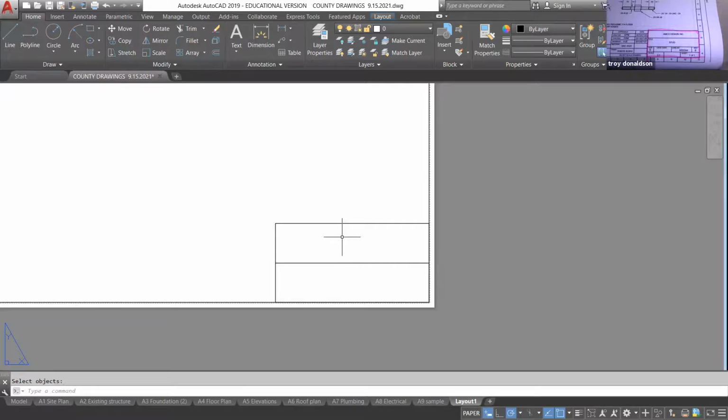If you've seen the offset command, it's super handy. I just type off, it comes up, offset. First thing it wants to know is your spacing. So I'm going to go up 0.5 because I think that upper section is 1. And then you just select it, boom, and send it. So that's how that works.